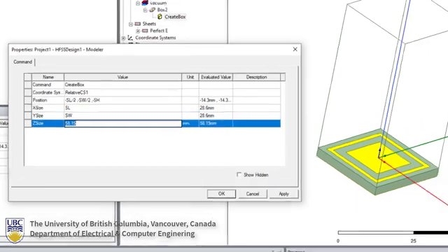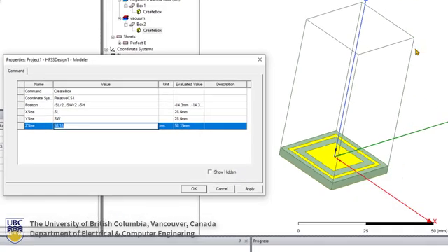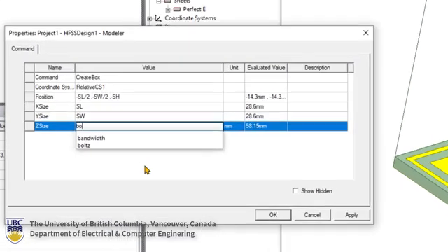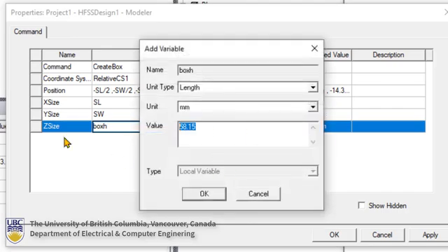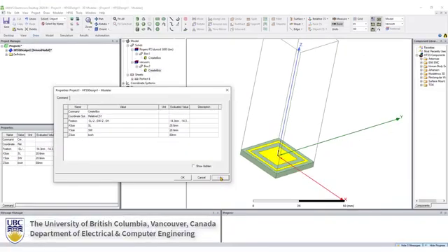The z-axis, the height of this box, I already talked about it in the previous slides, should be at least a quarter wavelength. That's the minimum requirement. This AMC works at 5 GHz. So at 5 GHz, I think 80 millimeter would be more than enough to satisfy the quarter wavelength dimension. So let me define a new parameter called box H for the Z and define it as 80 millimeter. All right. Okay.